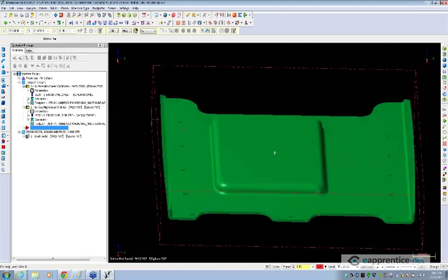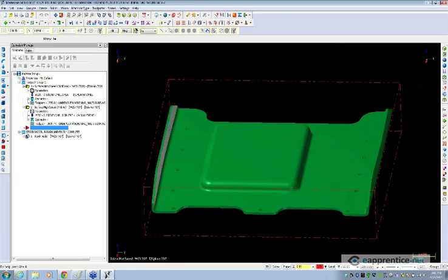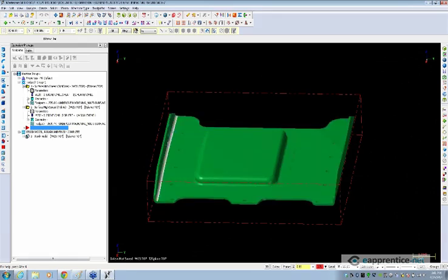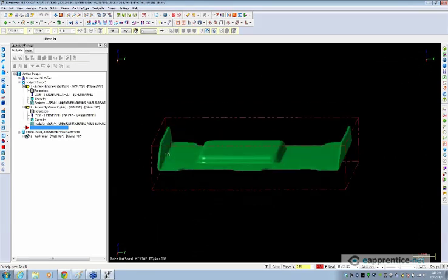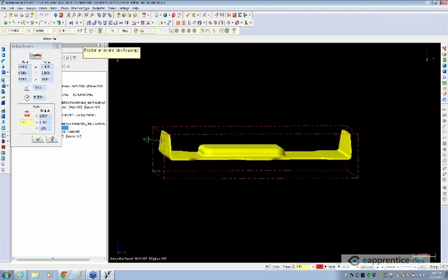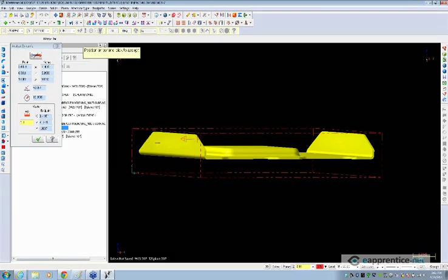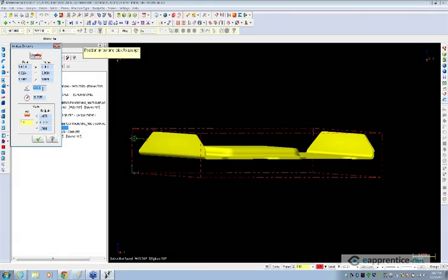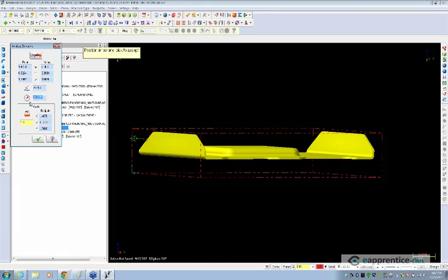So there is a tool, by the way, that will let you examine a solid face or a surface to see what degree that surface is either open or closed, if it's open or undercut, and that is Analyze Dynamic. So if I choose Analyze Dynamic, I can now go click on this solid face, and as I drag my arrow across that face, I'll be able to see changes in the angle of the surface. So this option here on the Analyze Dynamic dialog box will tell you the angle from vertical, and it'll also tell you the minimum radius of curvature.